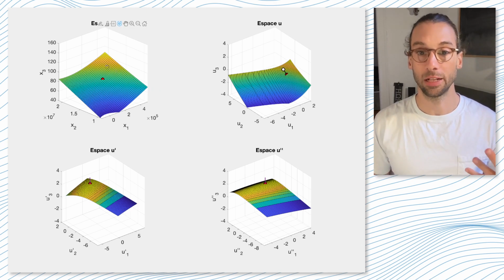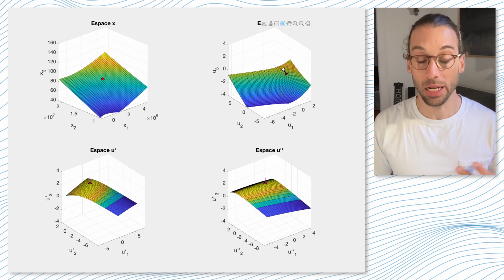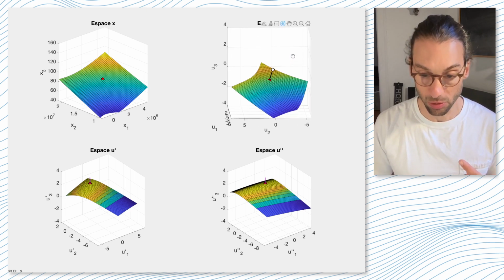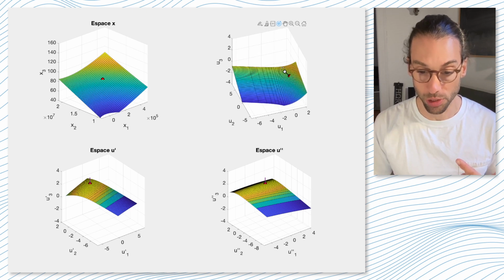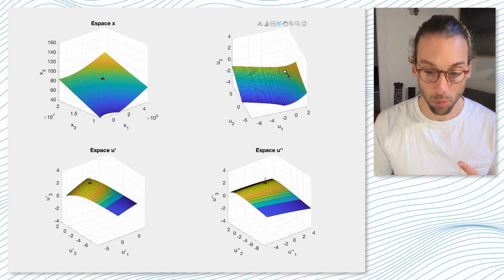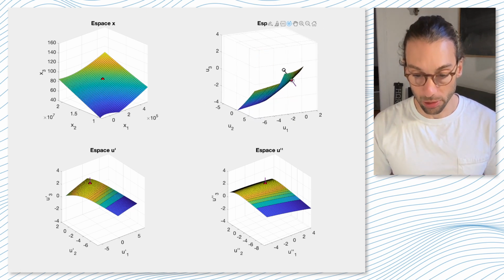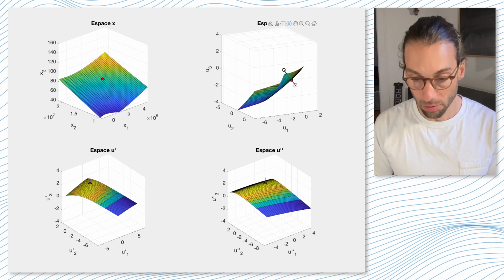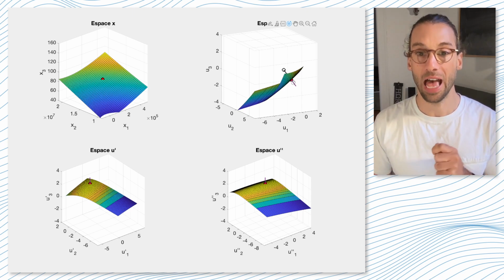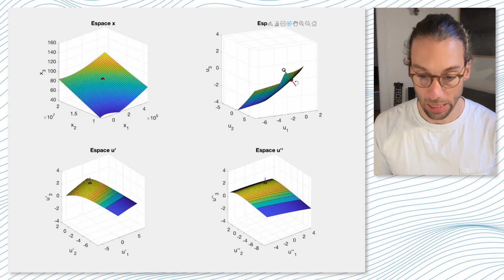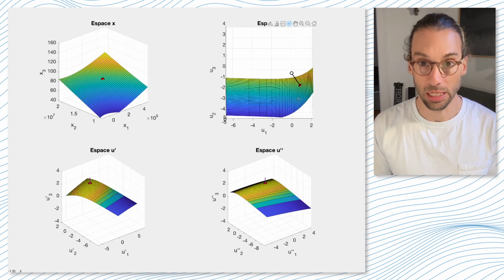Then, to do all the calculations and to find the design point, I went into the standard normal space. This is that standard normal space we're seeing here. This is the origin 0, 0, and the point is my design point U star. And you can see a little purple arrow, which is my alpha hat vector, my negative normalized gradient vector that points towards the failure domain, which is located somewhere here. So you can see that everything is around.